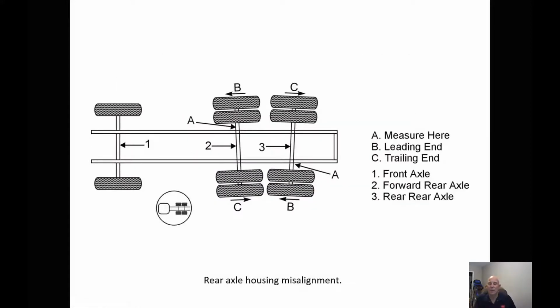The other thing we have to pay attention to is the housings, if they come out of alignment. So if the torque rod rubbers wear or something breaks, the first indication is that the tire wear will look off. Now, how we align axles we'll get into when we start doing frames and suspensions, making sure that is done properly so that they are in alignment and the vehicle is running down the road straight and not scuffing the tires.